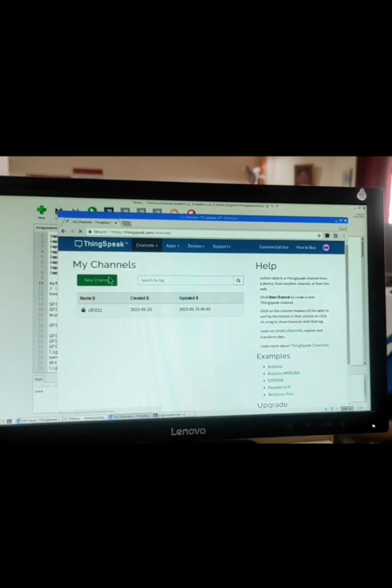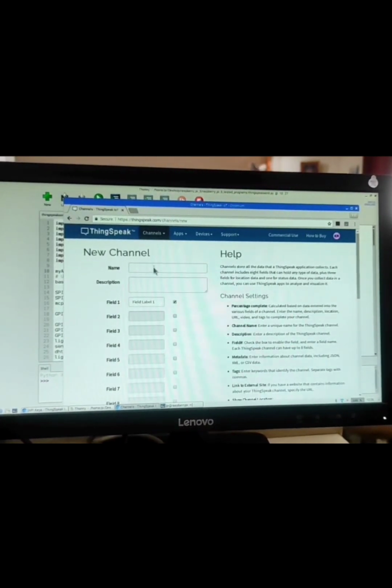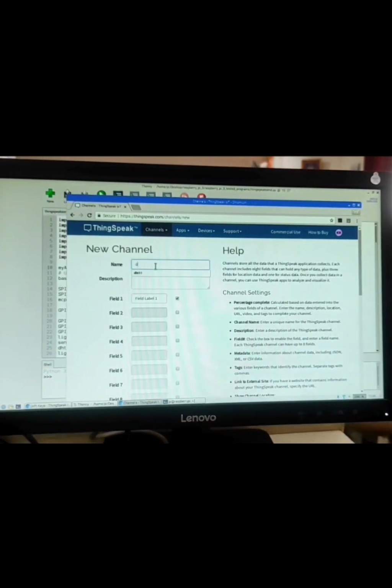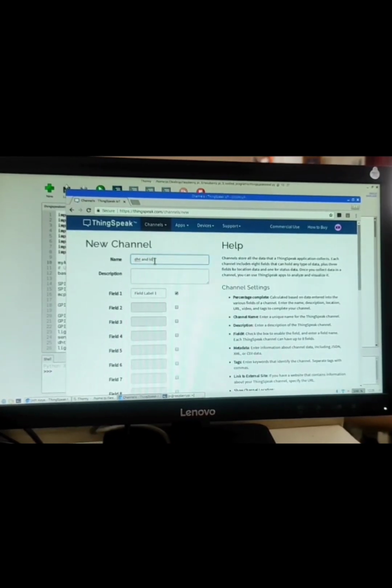Here in ThingSpeak Cloud, we need to just create a channel. When we create a channel, there will be My Channel. In My Channel there will be the following options. Here the name we need to give is our aim, that is DHT and LDR.